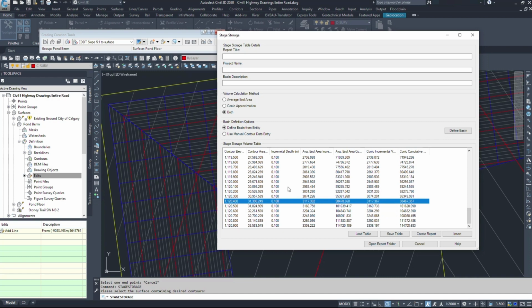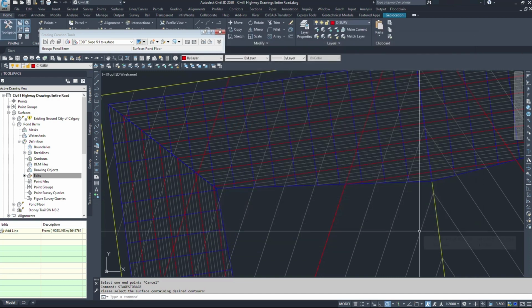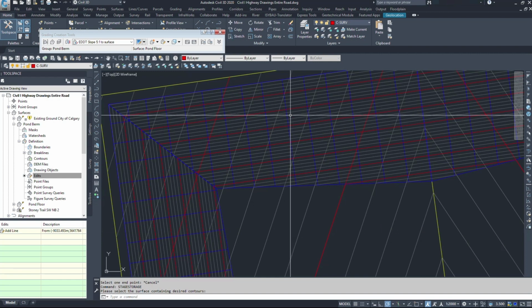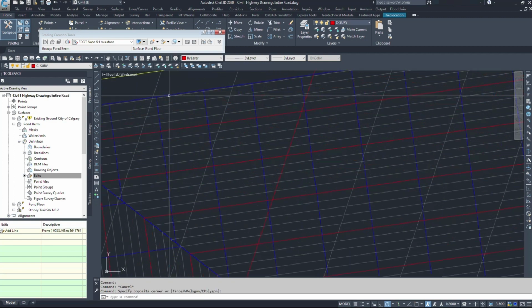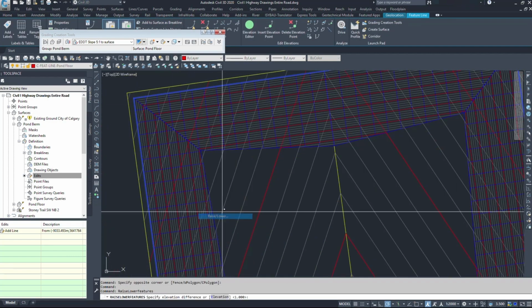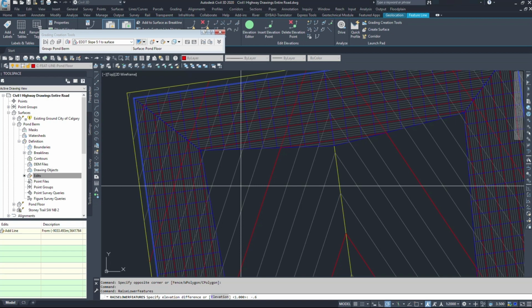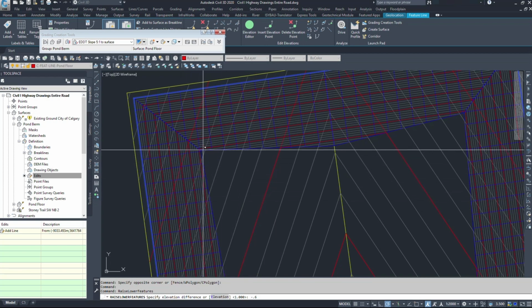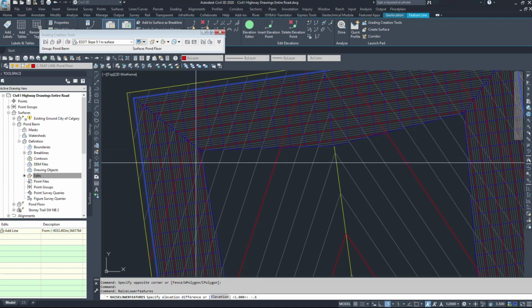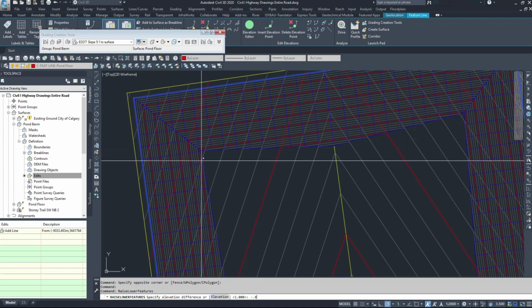Now this is easy to do. So we'll hit cancel. And again, you might have to play around with this a little bit, back and forth, raise your berm, lower your berm. It's going to be dependent on where you place your pond. I'm going to simply select my feature line here, this blue feature line. I'm going to right click, raise lower, and I'm going to drop it 0.6. Now the reason I'm dropping at 0.6 and not 0.5 is as the top of the berm drops, this toe will move out, therefore giving me a little bit of extra space. In fact, I might even go 0.8. So the berm will get wider on the inside, can theoretically hold more water even though we're dropping it, if that makes any sense. So I'm going to drop at 0.8 and hit enter.